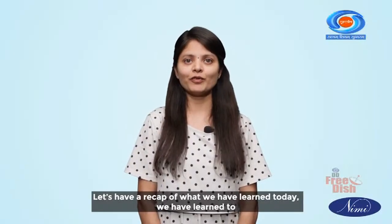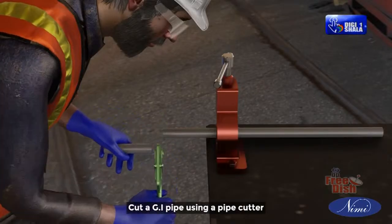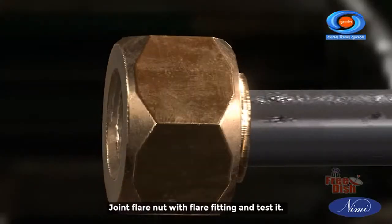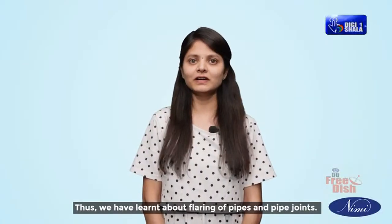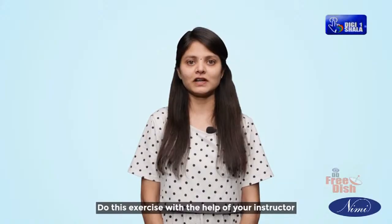Let's have a recap of what we have learned today. We have learned to cut a GI pipe using a pipe cutter, remove burrs using a pipe reamer, flare the pipe end, join the flare nut with the flare fitting and test it. Thus, we have learnt about flaring of pipes and pipe joints. Hope you have a clear understanding of this. Do this exercise with the help of your instructor.